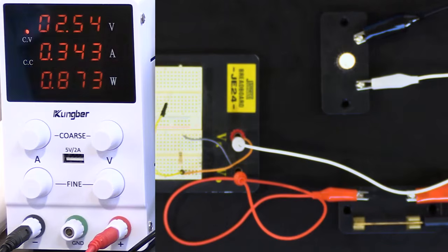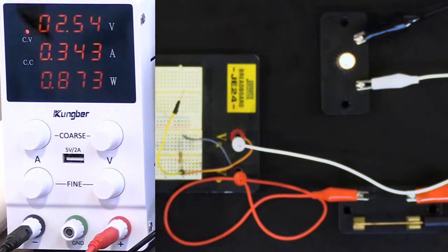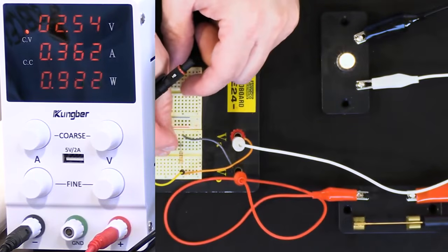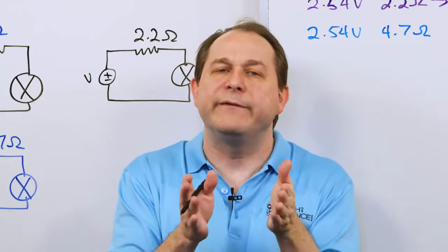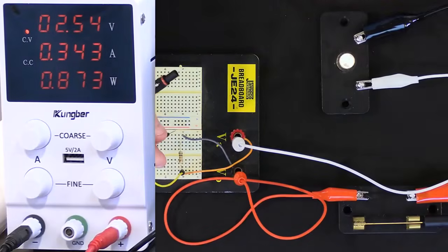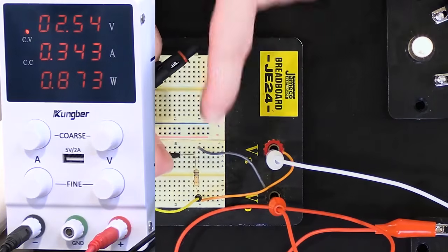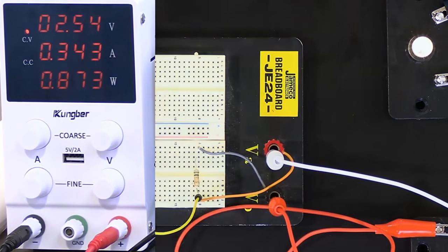That is because, you see, the electricity is coming out of the light bulb and going in here, and then it has a choice when it gets to this point. It can go through the resistance, right? Or it can go through zero resistance. Now, I told you the wire is not really zero resistance, but it's very low. So when the electrons get to the junction right here, they're going to always choose, they don't have a brain, but they always go to the path of least resistance, or predominantly the path of least resistance, which is circumventing or short-circuiting the resistor. And because of that, there's no resistance in the way anymore, and so the brightness of this bulb goes out. Now let me show you why this is dangerous.